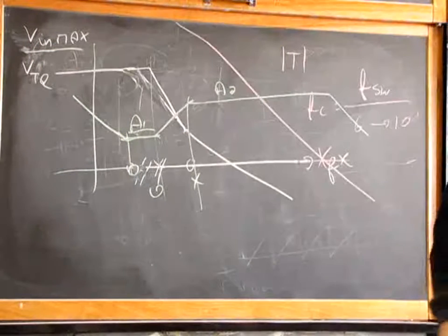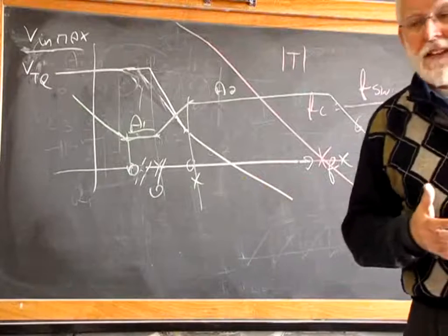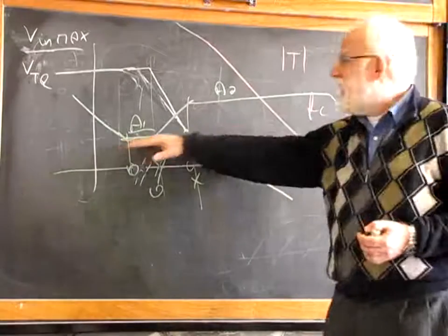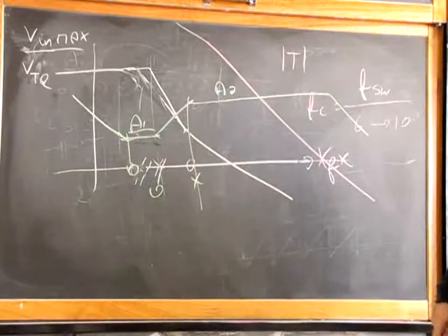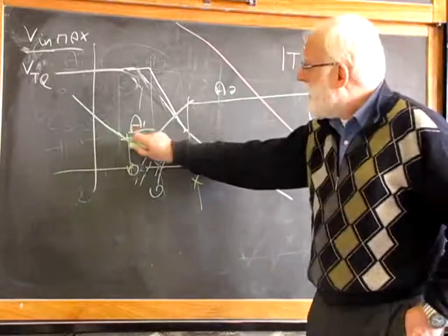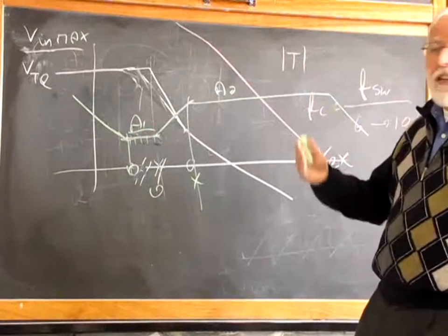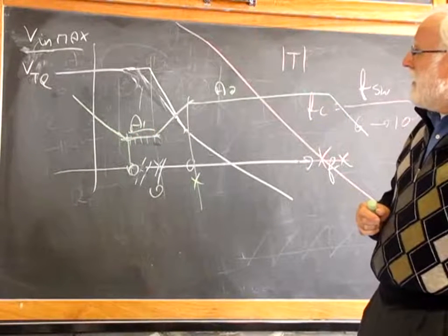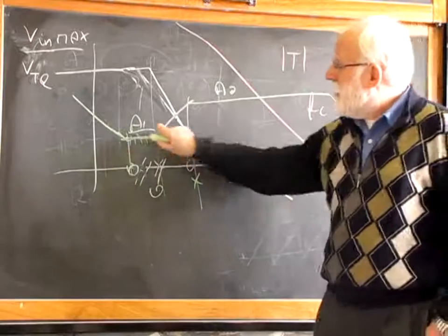If you look at the real, actual Bode plot using SPICE, for example, or MATLAB, you will never see this flat region and this flat region. You will even wonder if there is a flat region over there, but asymptotically speaking, there is. If you want to find A1, you have to pick any point on this flat region and determine the gain at that point.